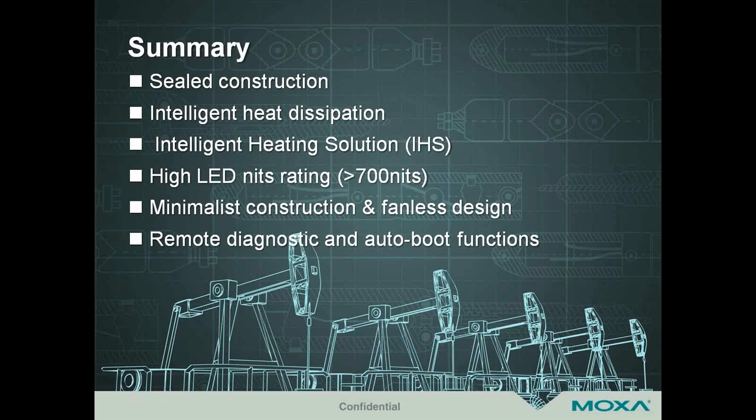It needs to be adaptive. It needs to have a constant sensor on the outside temperature and heat accordingly. So say it turns on at -5 degrees Celsius at a certain level, but once it drops to say -20 degrees Celsius, it goes to a new level. It's heating at a faster pace at a colder temperature. So that's one aspect of IHS. It's tiered, it's adaptive, it goes with the environment. It does not just turn on and off.